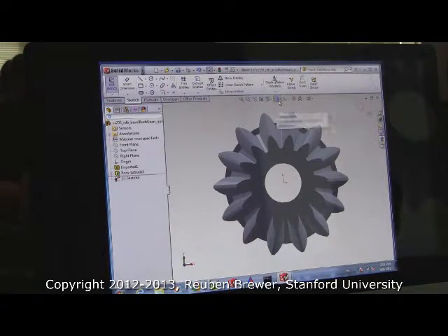Okay, go up to this button here and turn on the lines. See how circles appeared that we couldn't see otherwise? If you're trying to find a feature and you can't find it, the odds are that you're in the wrong display mode, so it's not shading something that should be, it's just blending in the background. So everyone's screen should look like mine before I proceed.